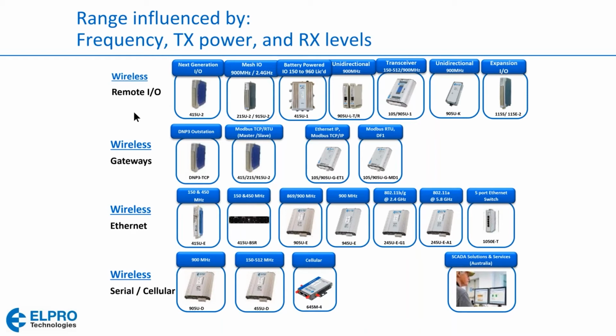Then we have the receive sensitivity of all of our different radios. Most of the radios that we manufacture, the receive sensitivity is around negative 110 dBm. However, we do make a number of very high-speed radios. These three products right here, high-speed Ethernet pass-through modems. And for those products, the sensitivity threshold is about negative 90 dBm. Now, those are threshold levels.